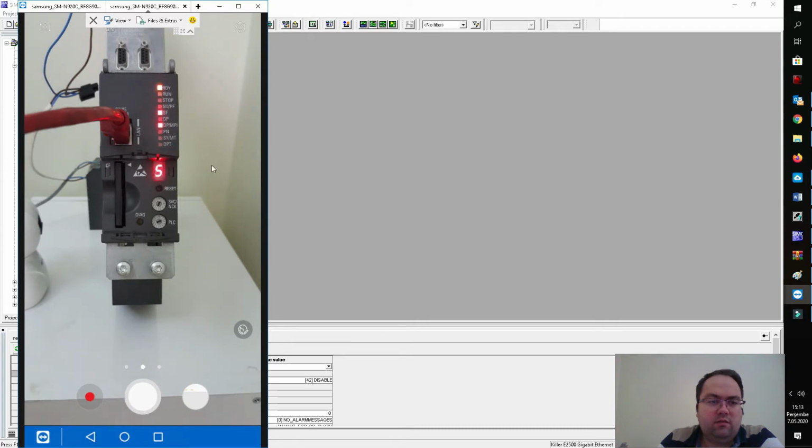Then it will execute the factory reset. The stop orange LED is blinking at 1 Hz. During the startup phase, you see different numbers here, and afterwards on your 7-segment display, if everything's okay, you should see number 6 and a red LED blinking.